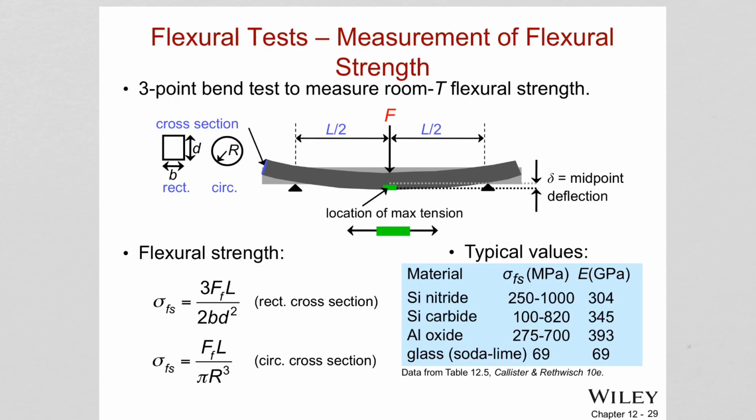Similar to that, strength can also be measured, and these are flexural strengths, or bending strengths. These will require the calculation of the bending moment and how far you are away from the center, which is called the neutral axis, because there is compression and tension on either side, and in between somewhere there is nothing. That is called the neutral axis.